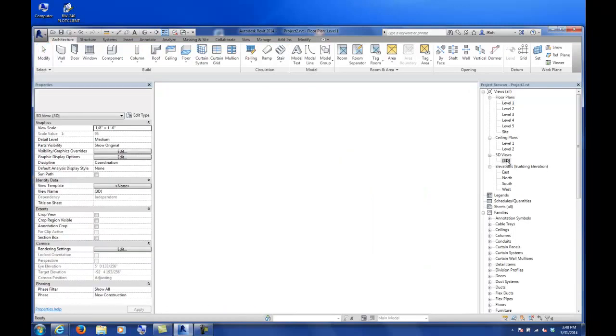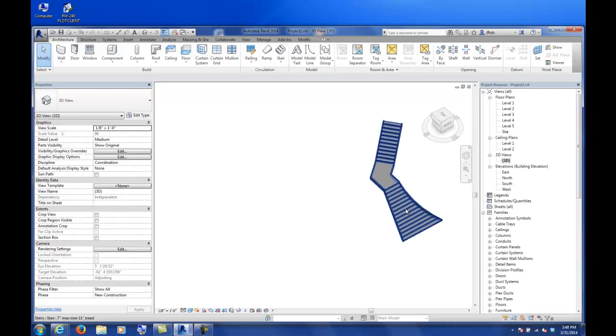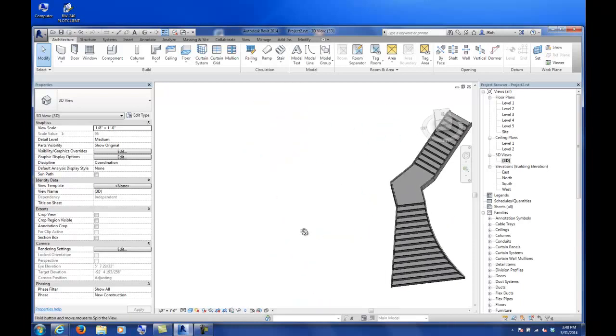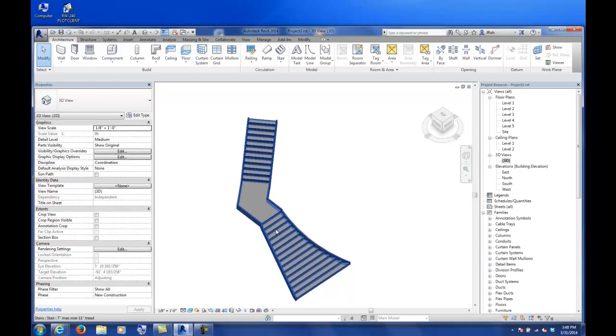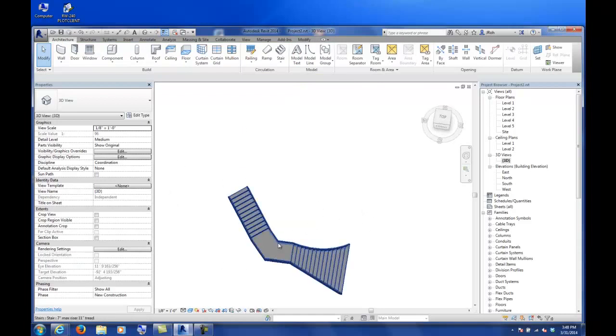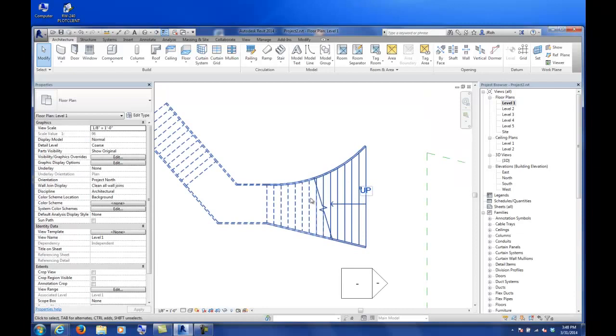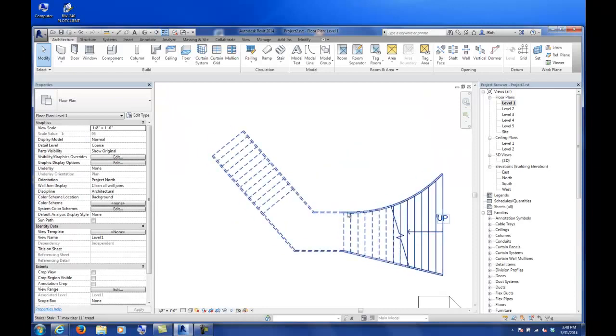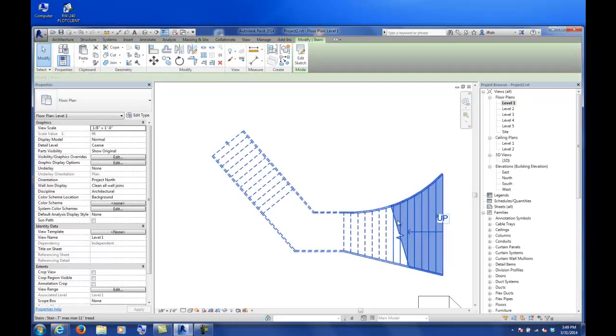So you can see by changing the boundary, you can start to get different designs associated with your stair runs as you move up through this element. So you can play around with those shapes. The key is, you can only have a boundary on either side, and you want that boundary to link up with wherever the edge of your riser is. So I don't really like that shape. Let me...